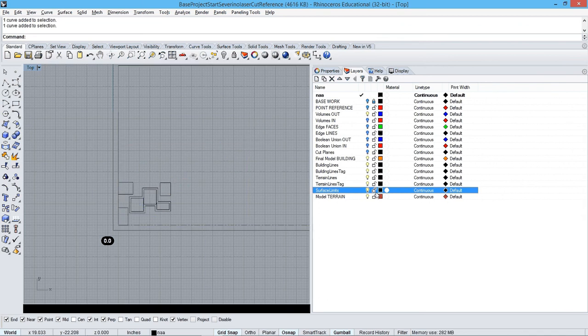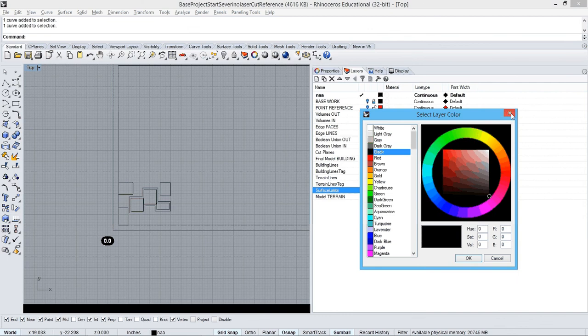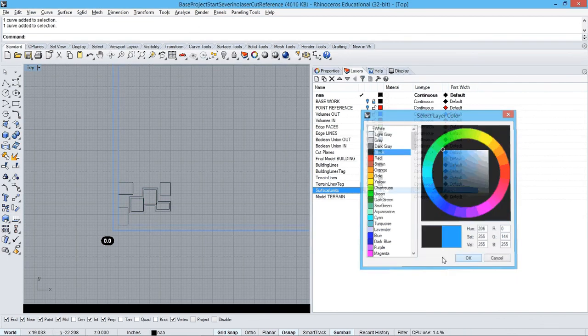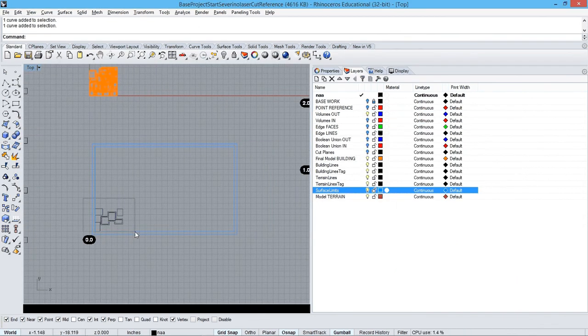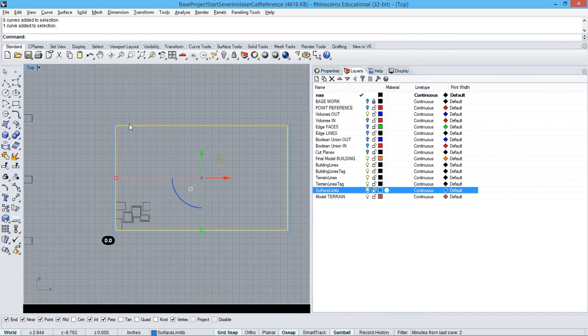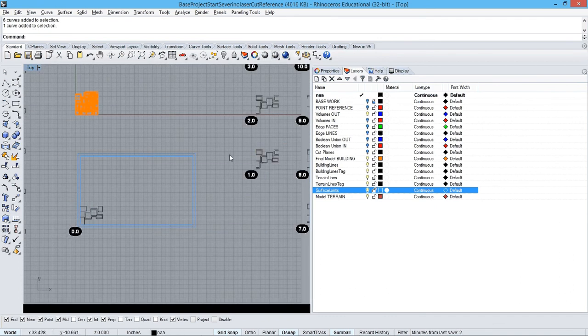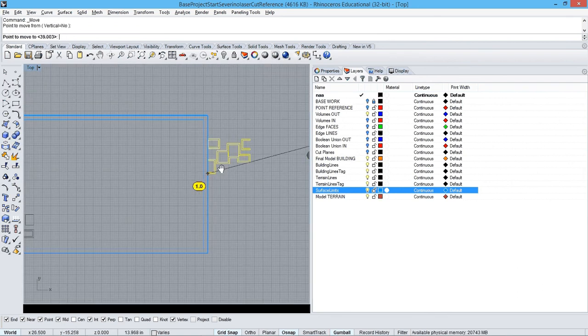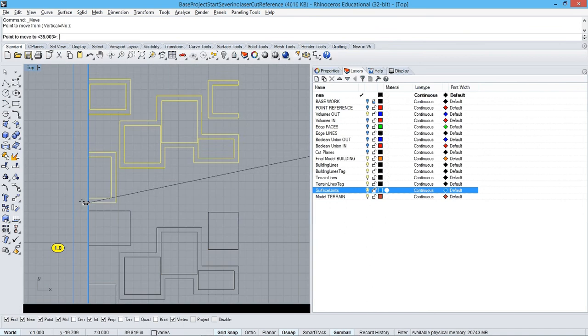Okay, if you want to change the layer for the surface limit to blue to make sure you see that all these curves should come inside of the interior offset curve. Okay, so you can select, put these ones carefully here, leave a little space,